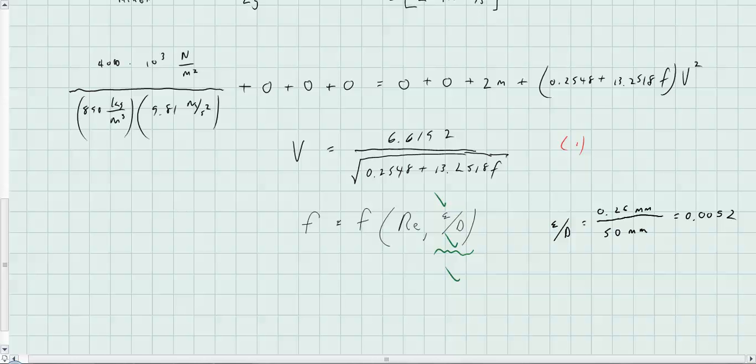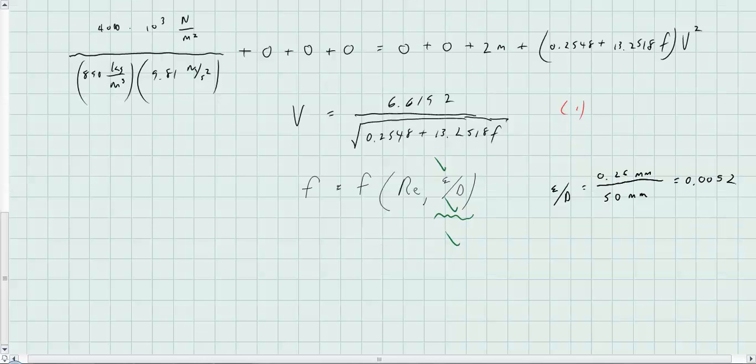That didn't give us an equation though. What's left? Yes, Reynolds number. Let's consider that. Reynolds number equals VD over nu. That's the kinematic viscosity version of it. So that would be V times 0.005 meters divided by the kinematic viscosity that they gave you.